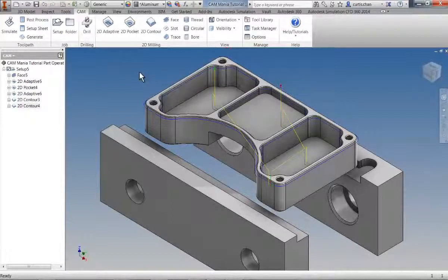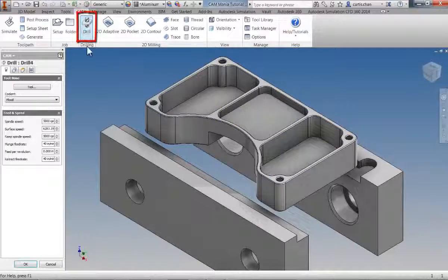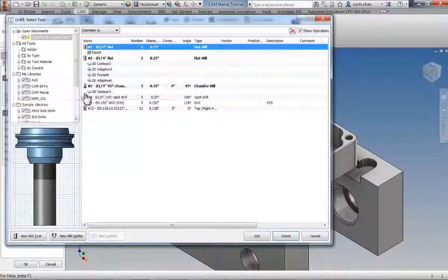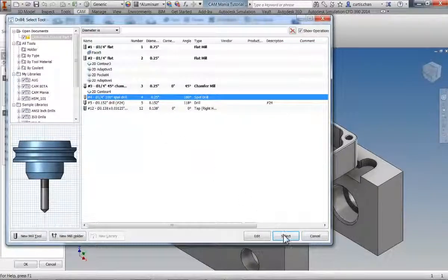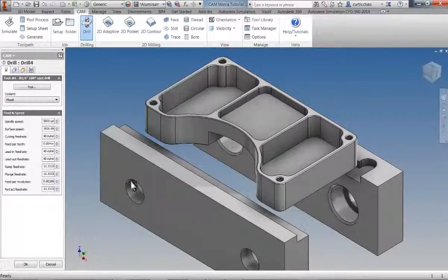We're almost done machining the part. The last task is to machine the holes. For this example, we want to machine 4 6-32 holes with a spot drill, and tapping operations. Let's get started. Click the drill icon, open the library, and select the 1/4 inch spot drill.